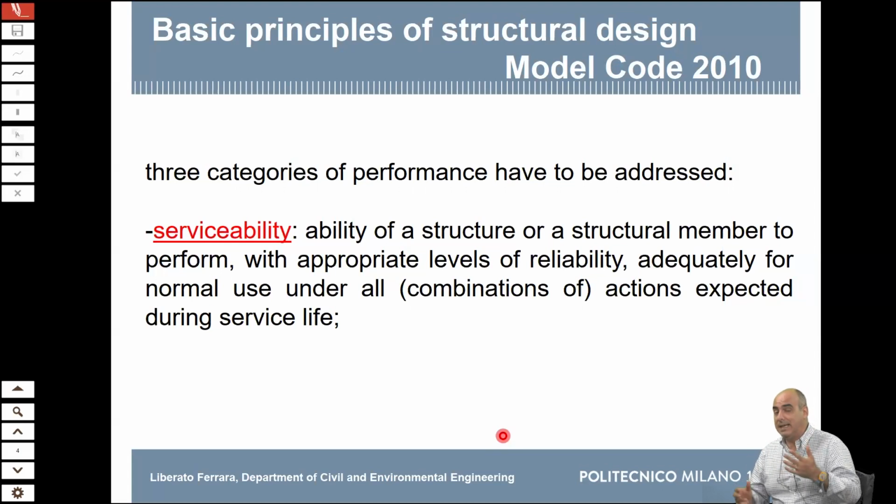The other thing is that there are some structural issues that, if you have an excessive sagging of your beam, what does that imply? Well, it might imply that your concrete has been excessively cracked. So you lose your stiffness. And if you lose your stiffness and the crack, you are loading too much the compressed part of the concrete, which will creep because concrete creeps.